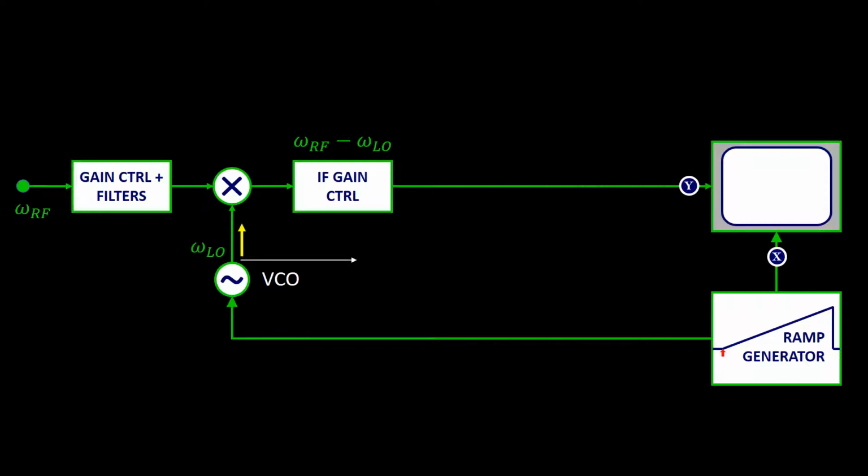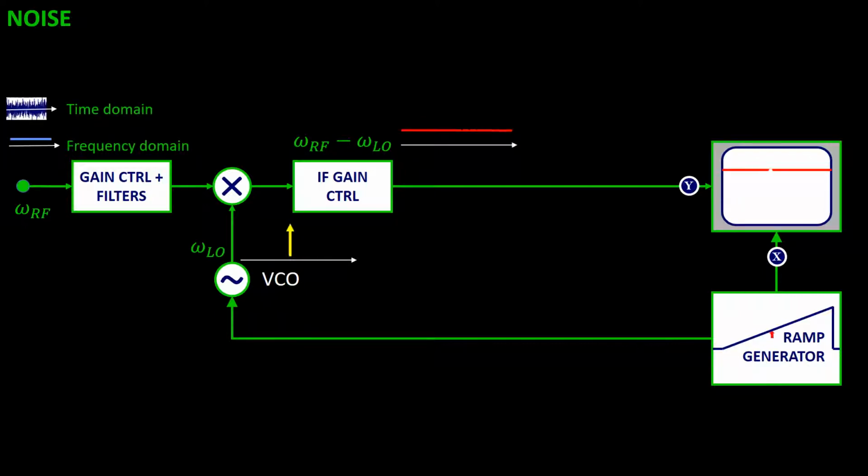Maybe the easiest way is to follow the same approach as before. We started by applying a constant voltage as a function of time. The equivalent in the frequency domain would be just white noise, for instance, thermal noise. We know that the spectrum of this noise is constant, so we just connect at the input a passive load at room temperature, and we see a horizontal line in the display. Nice, but if we try to measure a sinusoid, we will find the problem.